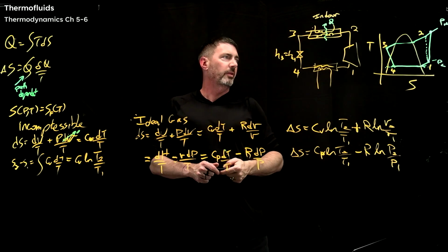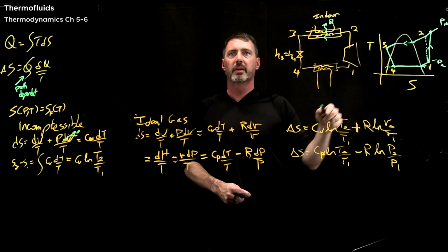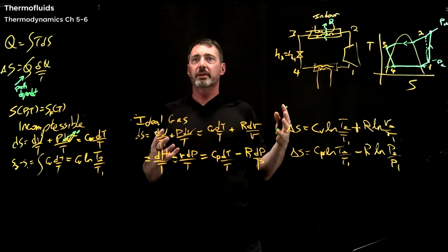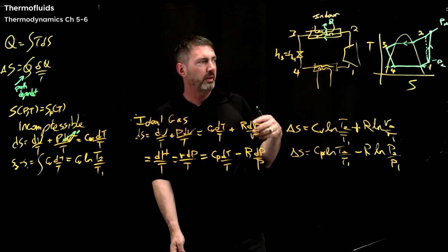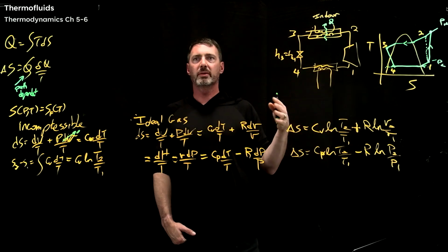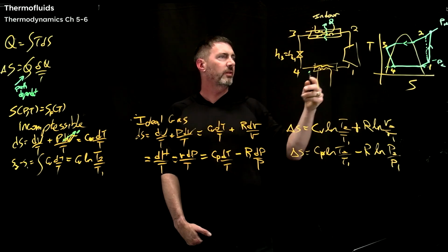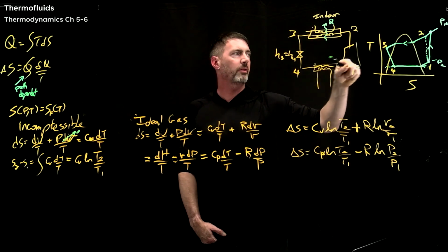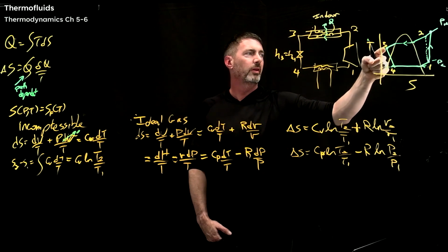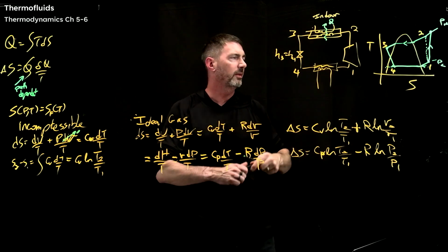Okay, and so on this cycle, you're actually running around the diagram this way. And you can see there's a good example of this in the book. You actually go through and calculate all of this. And the reason I'm drawing it is this is the first time you can really have real calculations. You can solve for how much heat am I putting into the house. Well, that would be the difference between enthalpies between state 2 and state 3.